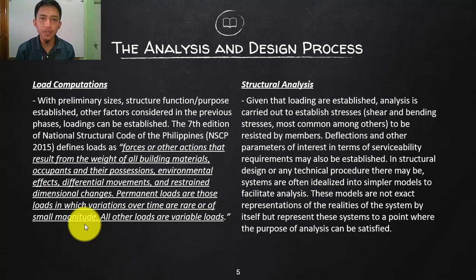to analyze this one. If you say analyze, based on the assumption of the sizes and the type of material of your building, we are going to analyze if that is capable of handling the loads based on what we computed in step number 3. So that is now the structural analysis. In building codes, as one of the requirements here in the Philippines, before your plans will be approved by the building officials, you need to attach this structural analysis. If you say structural analysis, that is the basis.